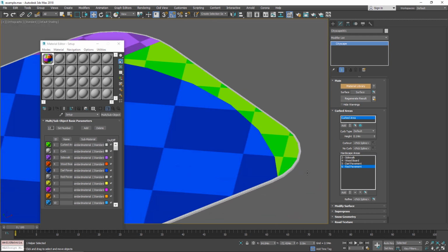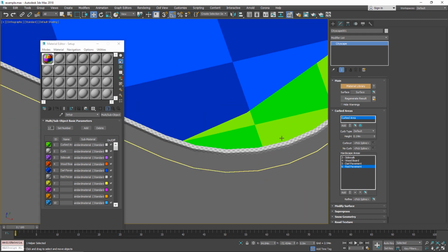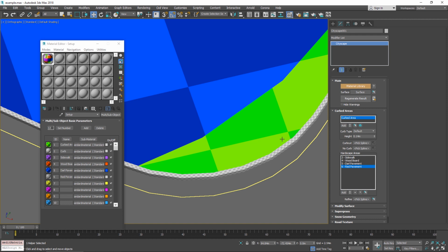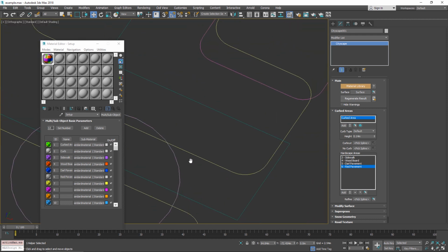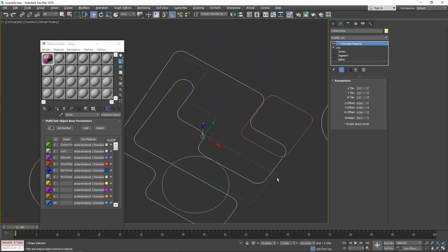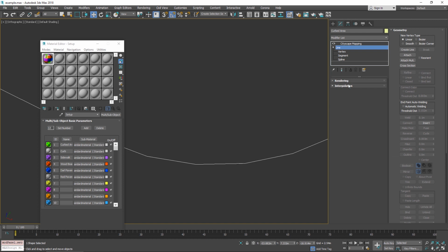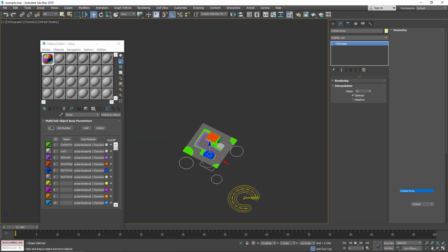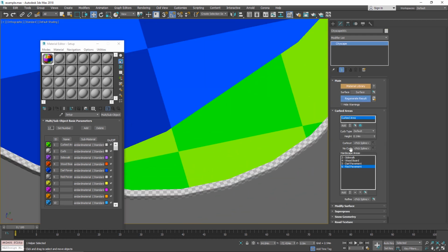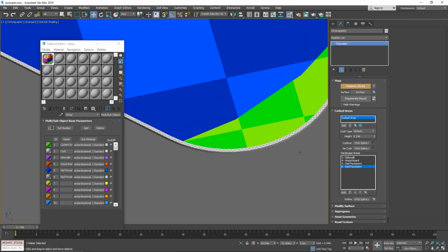So if you noticed, the corners of the site are a little bit segmented. You can see the segmentation here, and we can fix that easily by just going into the curved area spline, and we can either increase the interpolation from 6 to maybe 12. That's one way to do that. You'll just regenerate again, and you'll see that it will be much smoother.